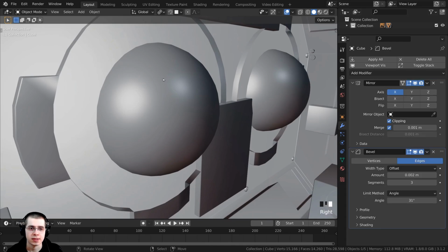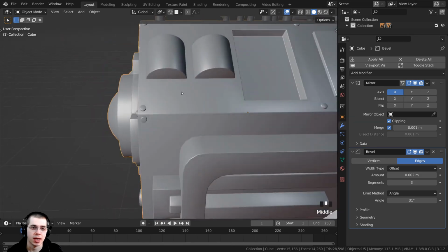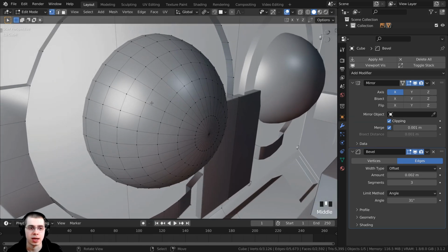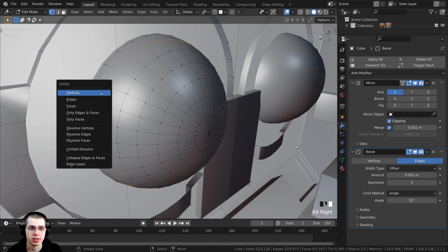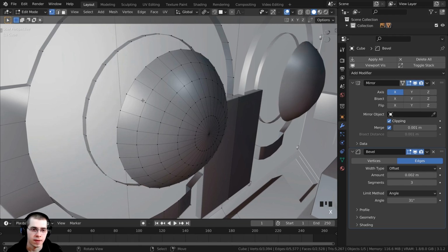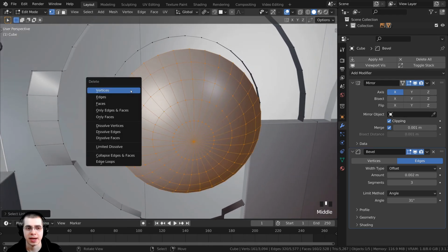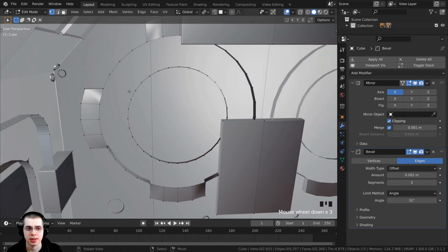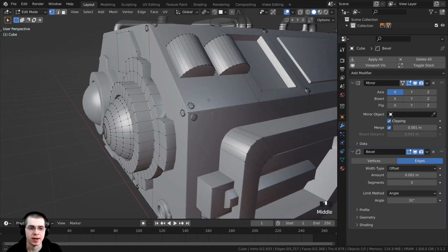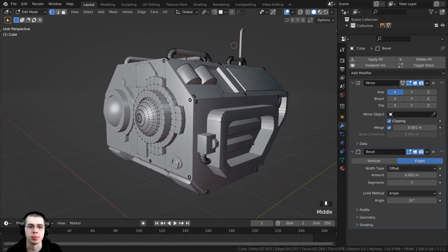So I'm going to select this object. Just make sure you select the main head object, and I can tab to go into edit mode. So I can now hold down the Alt key. I'm just going to Alt-select that ring of vertices, and then I can press X to delete, and let's delete the vertices. And then hover your mouse over this object and press the L key. That's going to select the linked vertices, and then I can press X to delete, and again we want to delete the vertices. All right, so now that doesn't look any different, but we have lower topology.